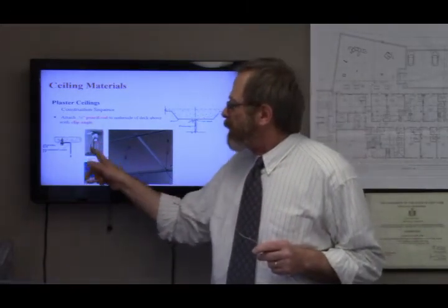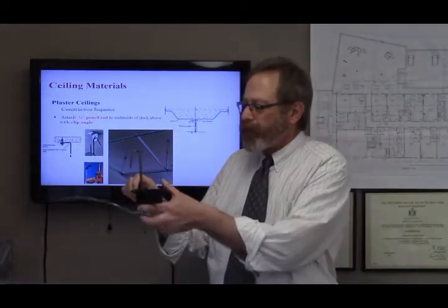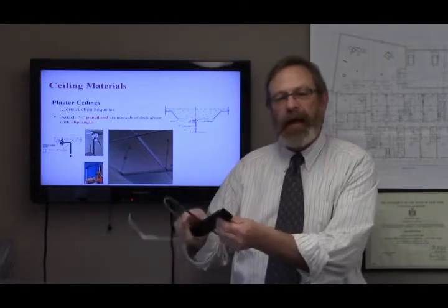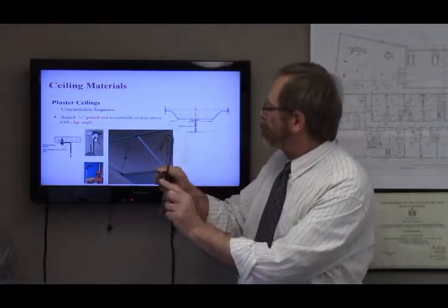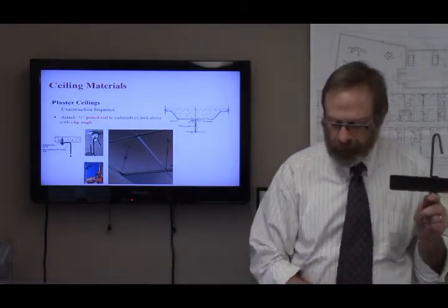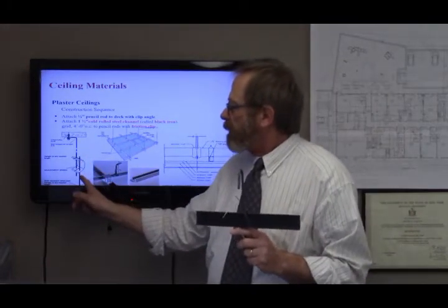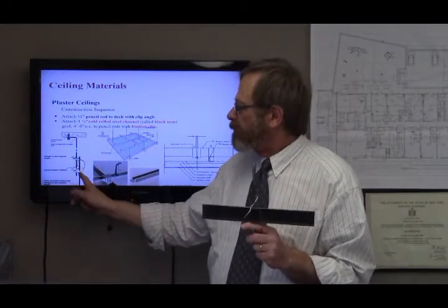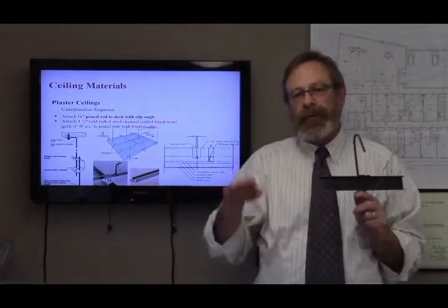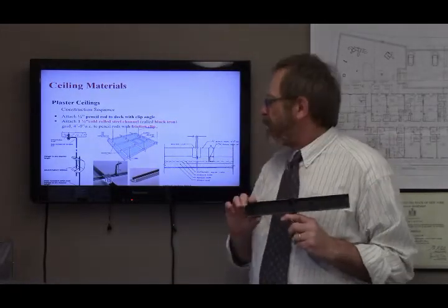We hang to that clip the pencil rod, which we've already spoken about, inserted the friction clip as well with the 1.5 inch metal channel, which we can actually extend down by adding an additional pencil rod to the friction clip in case we really have to adjust the height of the ceiling if it's really a far distance from the structural slab above.